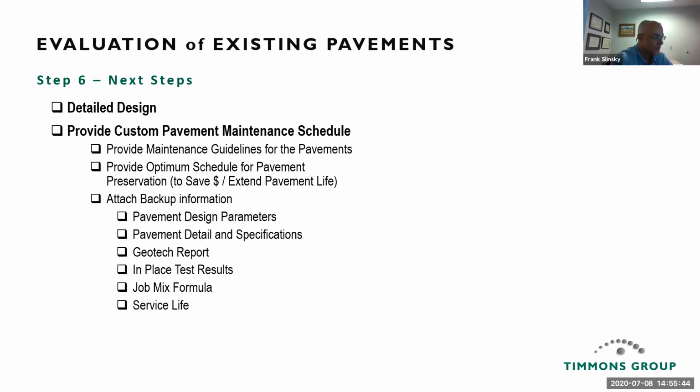And attach backup information. This is going to be your resource, kind of like an O&M guide, where you get your pavement design parameters in there. You have your pavement design and your specification, your pavement detail, your geotech report, your in-place testing results, job mix formula, and service life. So everything you need to know about that pavement is in there, including all the guidelines for that specific treatment that was done.